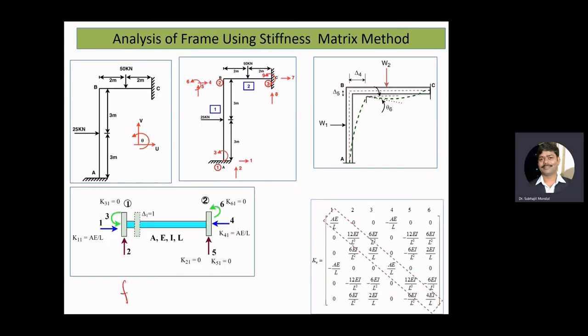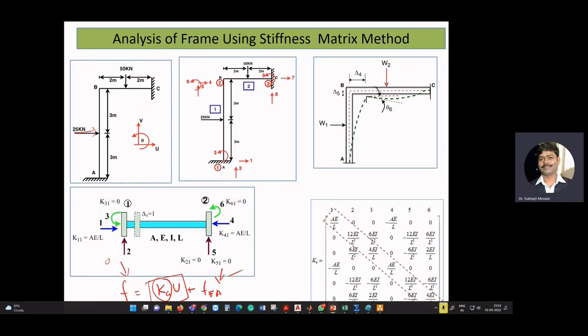Now we are going to solve KU plus F equals Q. Okay. Now our primary job is to find our global K matrix. This part either will be given, in terms of nodal forces. If not given, that means that will be 0. And this action we can calculate from our forces acting in the span. So the only quantities that are unknown to us are K and Q.